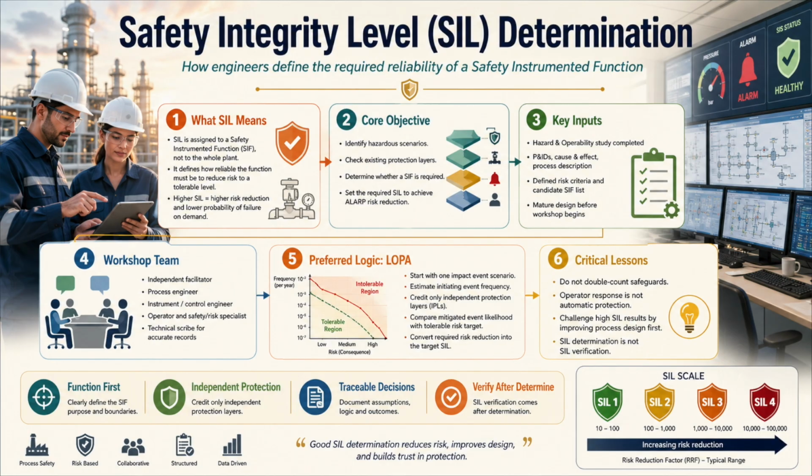That distinction matters. You do not assign a safety integrity level to an entire plant, control system, programmable logic controller, or shutdown panel. You determine the required integrity of each individual safety instrumented function against a clearly defined hazardous scenario.